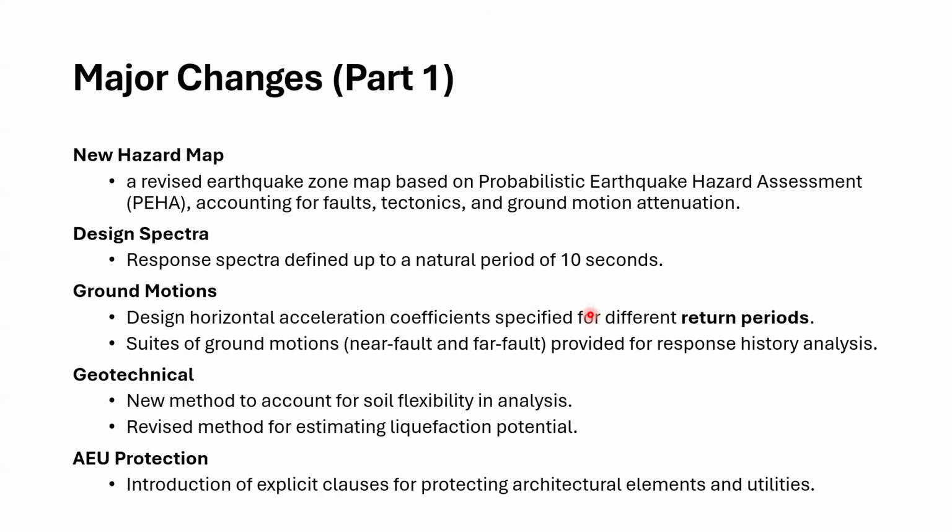Then the design spectra, which we'll be using, is now extended up to 10 seconds, and ground motions: design horizontal acceleration coefficients will be based on return periods. And suites of ground motions are also available for the response history analysis, also called time history analysis, for both near fault and far fault.